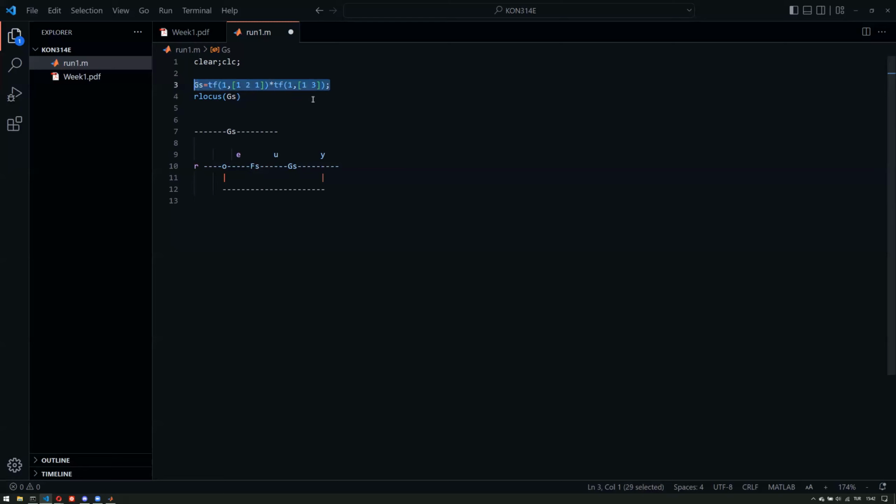So it's kind of plugging s into 0, because they cancel each other out. I can see that it has a static gain. So eventually the gain of the system is 1 divided by 3. So it's a third. Therefore, if I input something, 1 unit, the output will be 1/3. So if the input is 3, the output will be 1 unit.